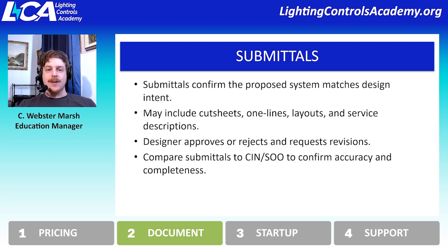So oftentimes when I'm doing a lighting controls design, I'm going to break out all of the documents that I've issued for that project and go very slowly through all of it, through the submittals, to make sure that everything aligns with what I had specified. Because if there was a missed piece to the project, that submittal is the record, and if I've approved it and there's a room missing or a bunch of devices missing and I've approved it, well, that's on me because I overlooked that and said, yeah, it's fine. So I'm going to really spend a huge amount of time just reviewing the submittals and making sure that they are accurate and up to date and cover everything that I need them to cover.